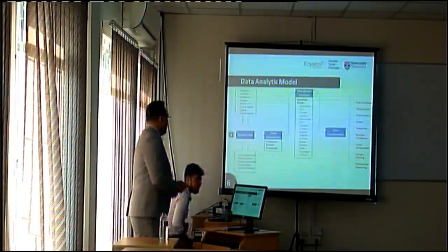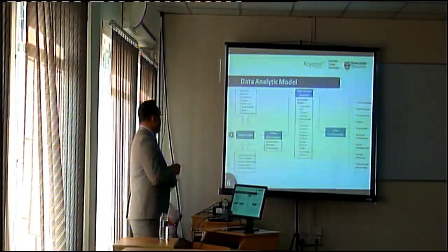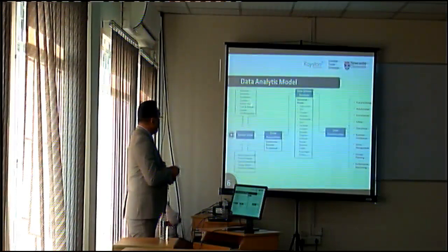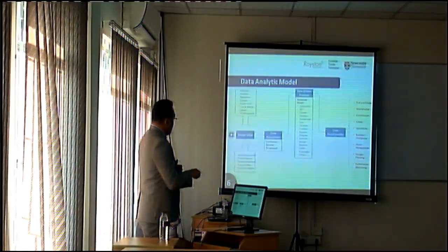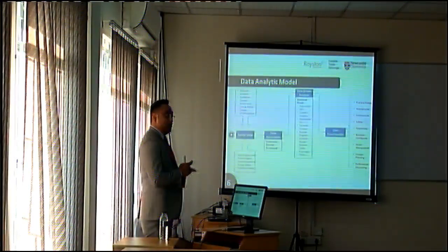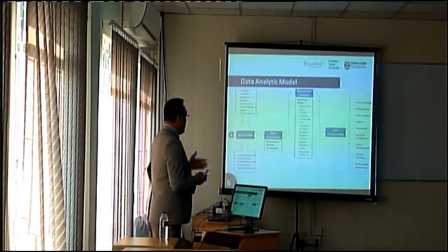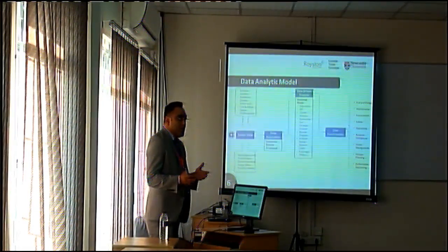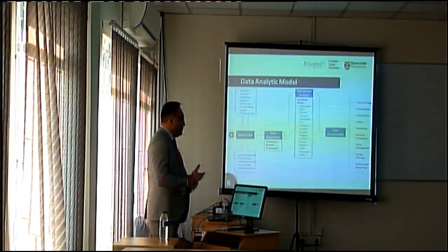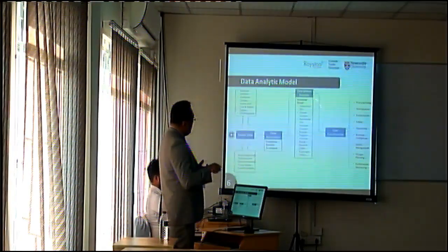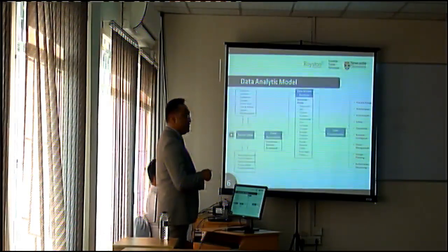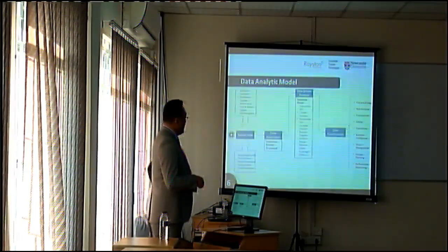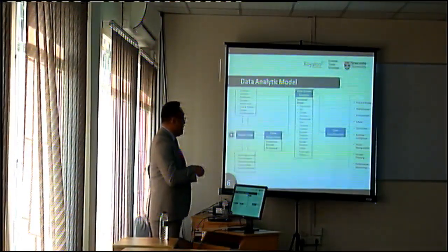This is the model. You can see the sensor data: we have an emission monitoring system, and data for the ballast water, main engines, and diesel generator using a torque meter and fuel flow meter. All the data comes through three different ways. It will be continuous, it might be discrete, or it might be demanded by the operator. It might also be some known data from the manual. Then we build the statistical model. Different statistical models are used, like regression, statistical process control, and cluster analysis. We use fuzzy logic and artificial neural networks.